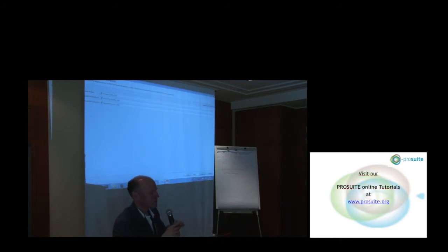And then another point of linkage is the LCA software has this LCA method, as I had explained, and the method contains several endpoint categories, and these have specific names, but of course you can have arbitrary names. This suite method has human health, natural environment, exhaustible resources as topics, and therefore you need to assign here which category in the method corresponds to which name in the proceed method. So I could also select something else, but that wouldn't make much sense. Yeah, but this is essential. Otherwise, you also don't have an established link.